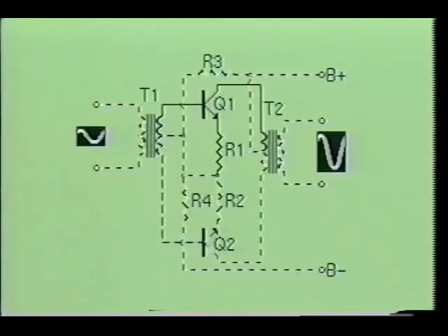As you saw earlier, distortion cannot be avoided in a Class B amplifier. Therefore, it is common practice to drive the amplifiers as hard as possible to obtain the maximum efficiency. Class B amplifiers are used where high efficiency and high output power is required and where a small amount of distortion can be tolerated. The typical efficiency of the Class B amplifier will be around 50 to 60%.